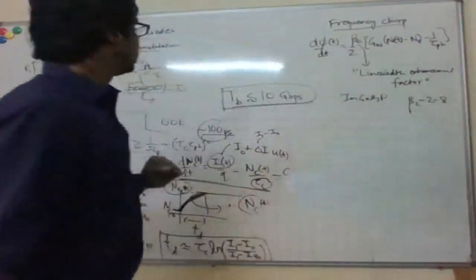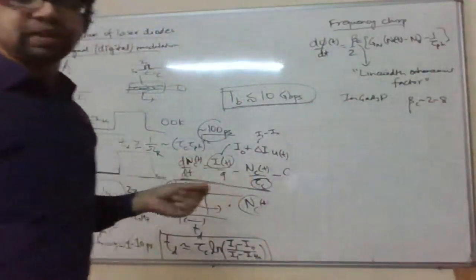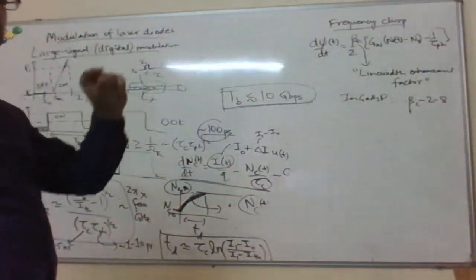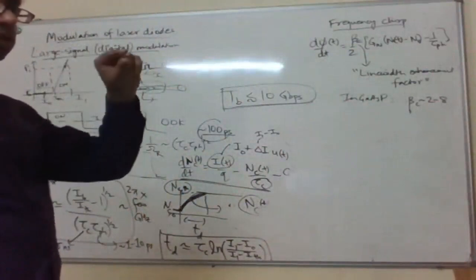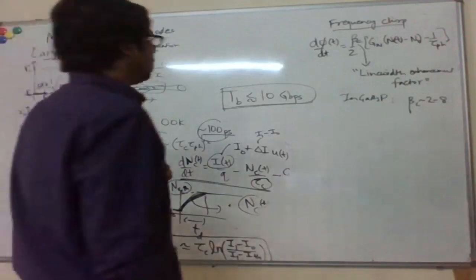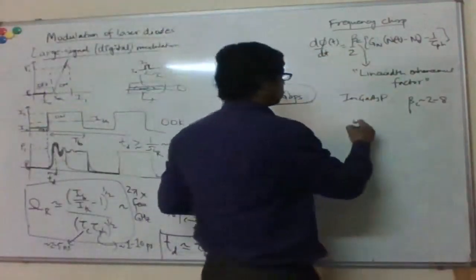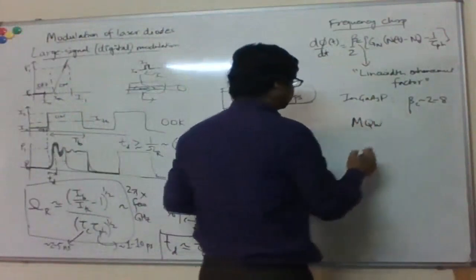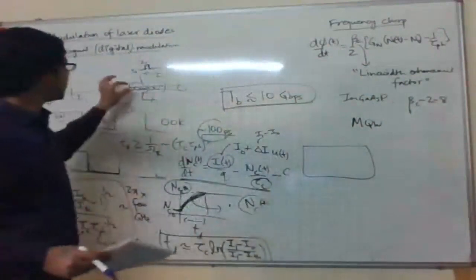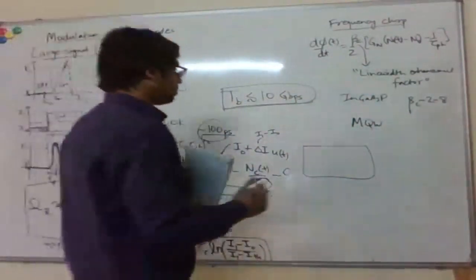Okay. So if you make the active region really, really thin, so we discussed this briefly, you go into this quantum well regime, on the scale of tens of nanometers of thickness, then you can make this effect really small. For so-called multiple quantum well lasers, for the standard devices, the active region we saw was typically like 100 nanometers thick.